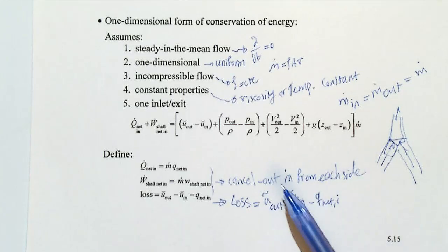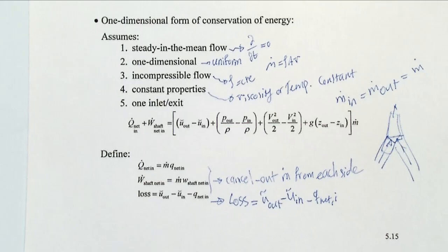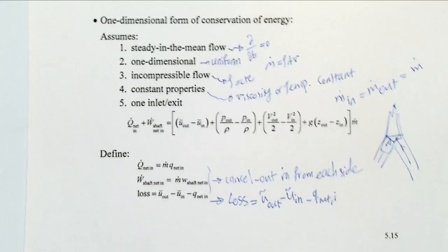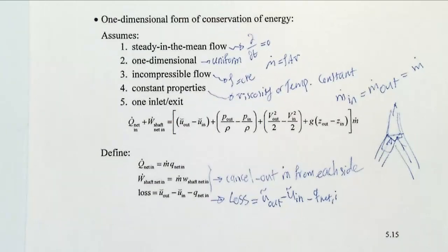That's the Bernoulli equation. It means that if you don't have any loss, okay, what was the assumption for Bernoulli? It has to be over the streamlines, steady state, incompressible, and one-dimensional, input and output incompressible, constant properties, and steady state over the streamline.